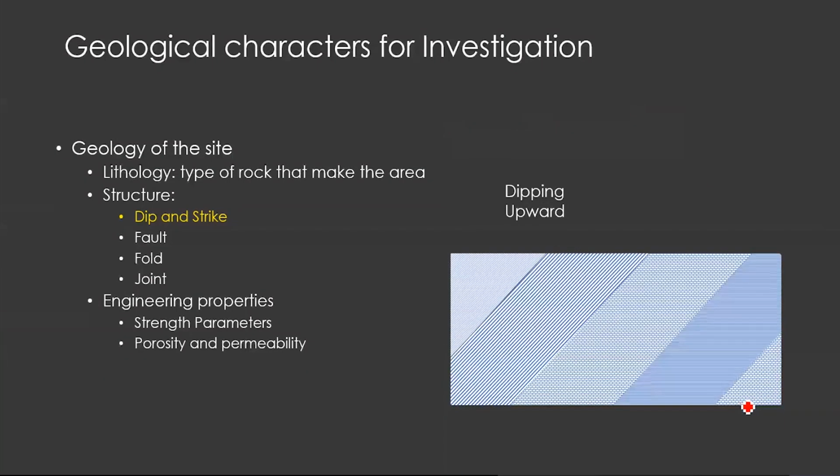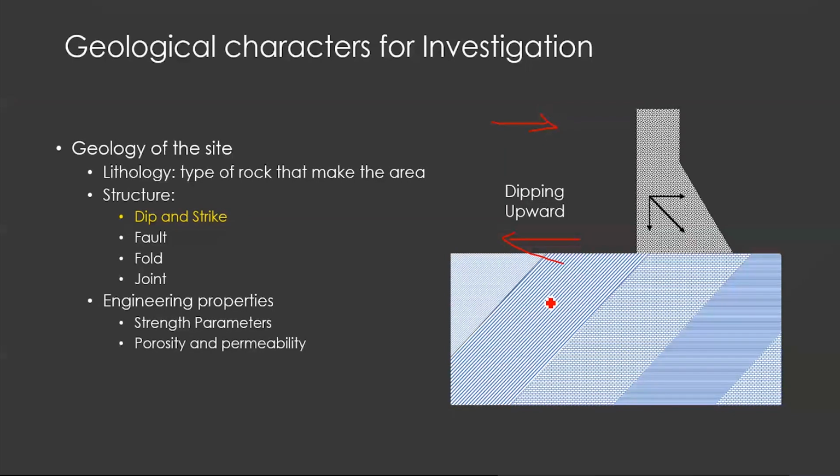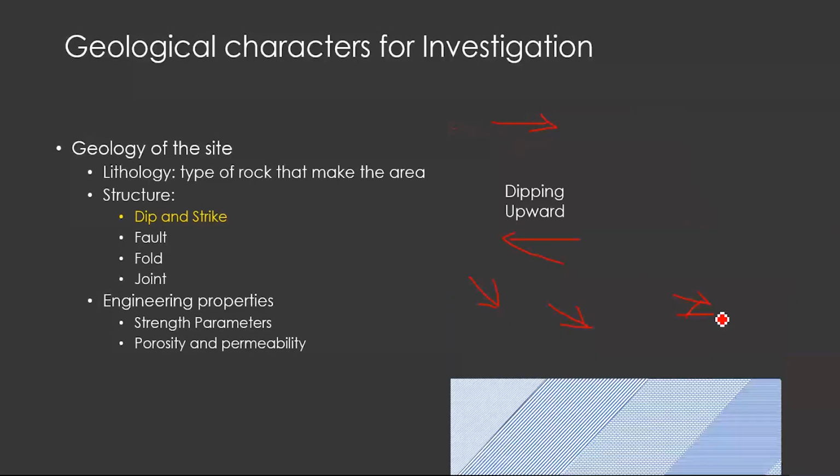Now the third situation is that the rocks are dipping, but in an upward direction. This is the flow of water, and the rocks are dipping upward. In this condition, the force acts perpendicular to the bedding plane, so we assume this to be the most favorable condition. It doesn't mean that the other conditions discussed should not be considered; if we don't have any other option, we may even consider those options. But given these three conditions, the last one seems the most suitable.